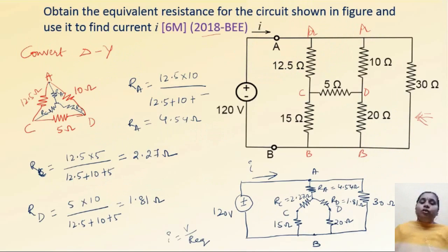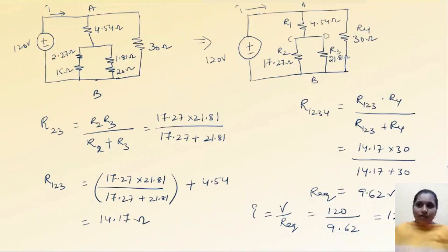First you need to verify whether the circuit is in series or parallel. Then you need to check if it is possible, then you can solve it easily. If you find it difficult, that is, they are not connected in series or parallel, then you need to see whether they are connected in star or delta. So if they are connected in star or delta, you convert one form to another form and you replace the circuit from where you have taken that form, and you can see that there will be a series and parallel connection, and you can solve it in this simple manner.